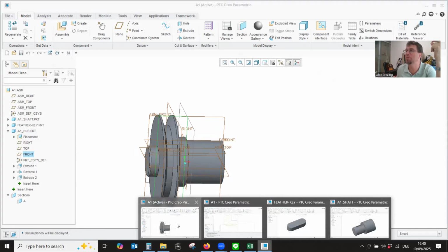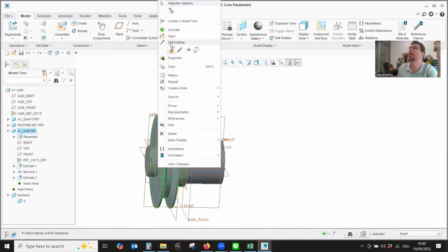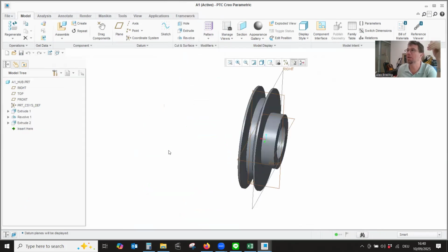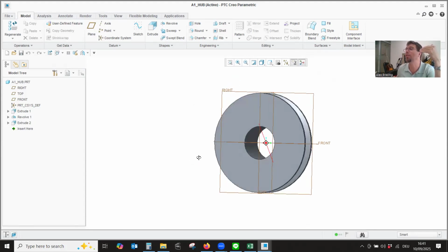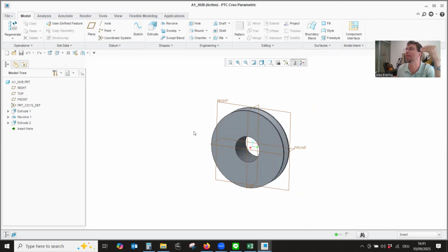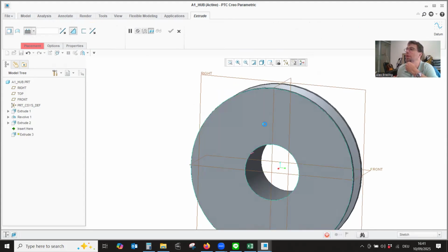So let's go into the part. I haven't opened my part yet, no problem. Let's just open it from here. Open the file. So I left-click, right-click, groove. And this time it makes sense to sketch and model the cut similar to the manufacturing process. And we remember that what we're doing is we're pushing a broaching needle into that hole. So why not sketch it exactly like that? So I'm creating a cut. Here the depth is not defined by number, but it goes all the way through, and I sketch on that surface.